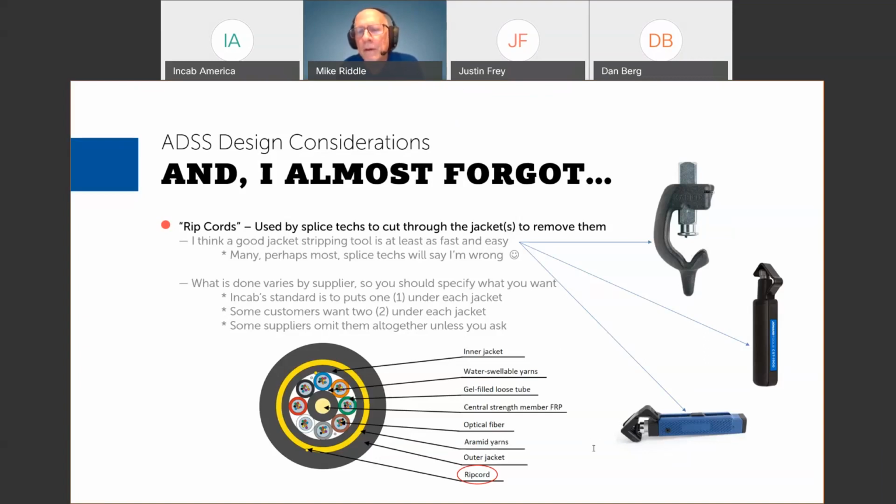Something came up. If a wedge dead end clamp is used in network, then how can one avoid elongation of the jacket due to tension? It is a common issue with dead end clamps and ADSS cables. For ADSS cables, I am not a fan of wedge dead ends. In my experience, I know of a number of cases of jackets ripping with wedge dead ends, and in recent memory, I can't think of any that happened with the formed wire dead ends.